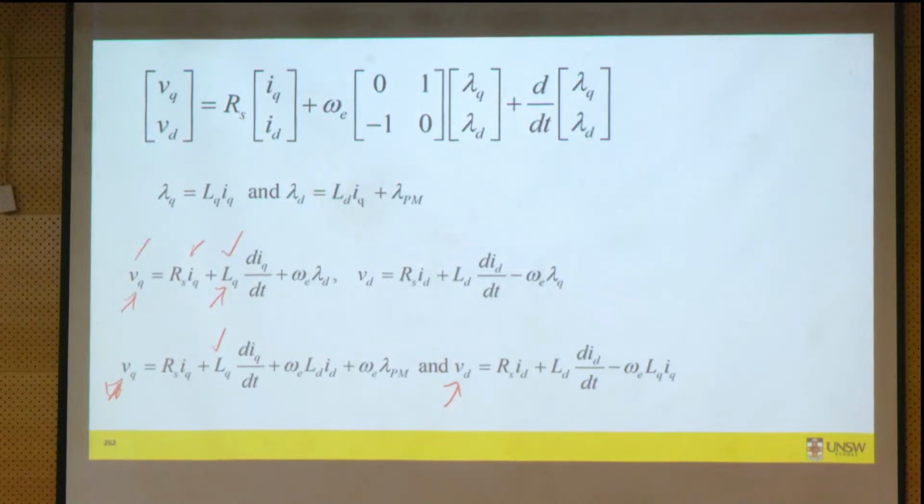Using these two equations, we can even use Laplace transformation if we wish to analyze their responses, just like a DC motor. Or we can use these two equations to develop models. Like in Simulink, some of you may have got exposure to the Simulink PMSM model, right? If you open that model and go under it, in fact, they have only these equations. They only do the torque calculation or the response calculations using these equations, okay?